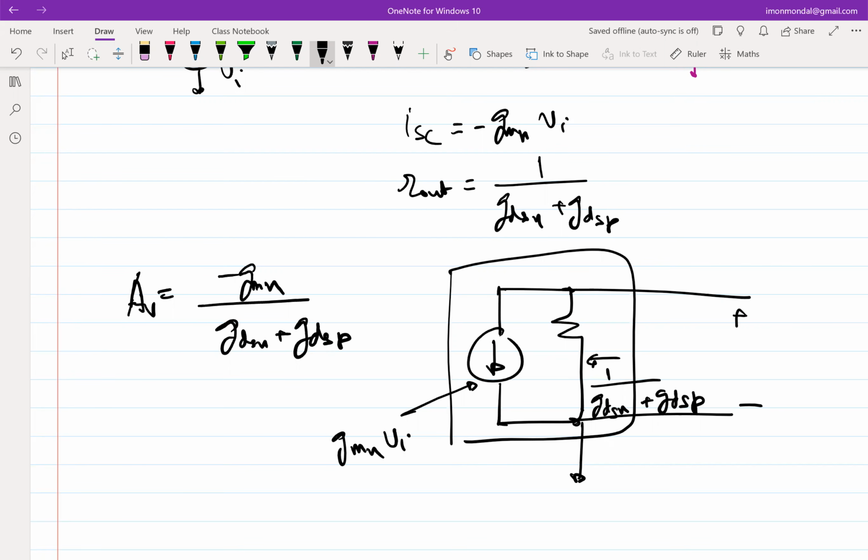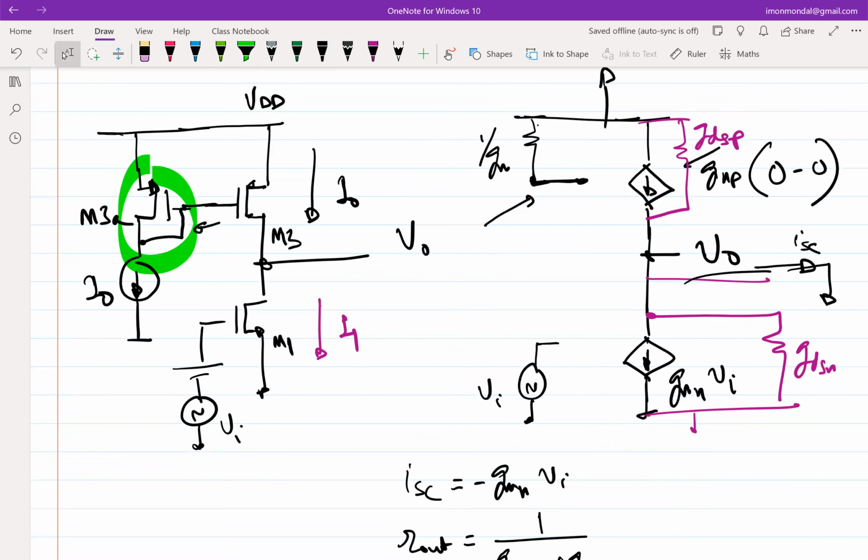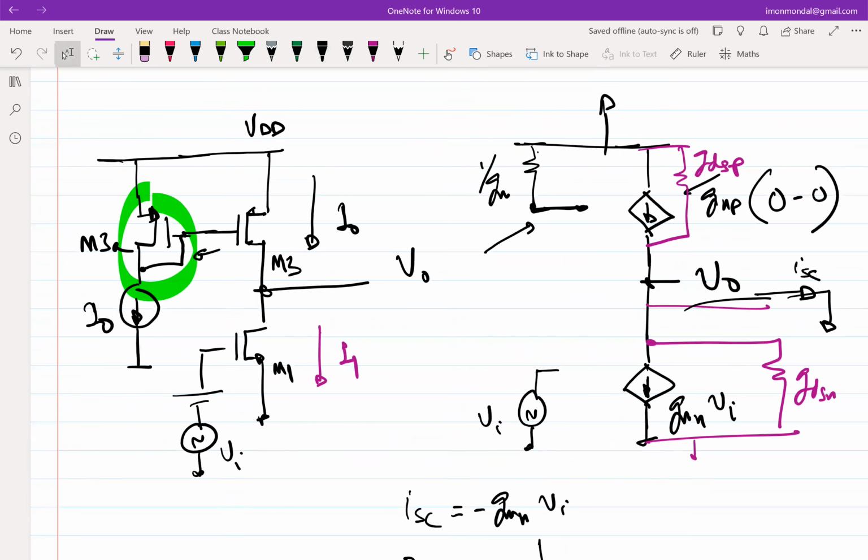Okay. Any questions? Sir, yes. The last circuit, why have you replaced it with that battery? So what you are essentially asking is that it seems like there is one I0 from top, one I1 from bottom. It's a problem, but you have to recognize the fact that we will not be using this as is. It will be a part of a broader negative feedback circuit, which will ensure that I0 equals I1. I am essentially assuming that there is a negative feedback controlling this battery, just for analysis purposes. Yes.